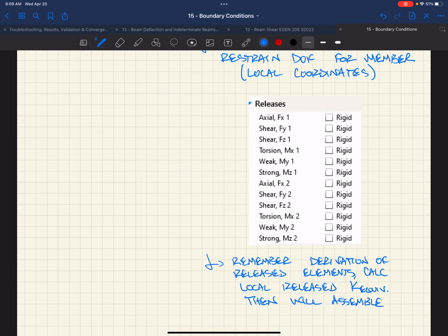You could, I guess, make axial, shear, and moment all rigid, right? You would have to release all degrees of freedom at the end, on one end. Yeah, I've never tried that. In my head, I wonder if, like in class, we were saying you could either make your boundary conditions on the nodes or through the members, and you can achieve the same behavior with releasing either the member or the node.